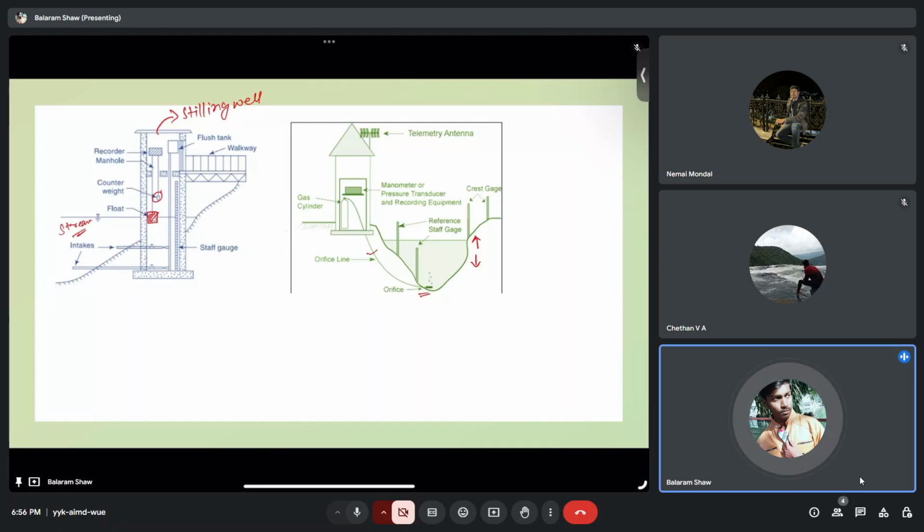And from that rating curve that I just mentioned, which is a very simple thing but very important, and gives a significant amount of information, we get the discharge, that is, how much stream flow is happening in the river or streams. The rating curve for a specific stream location is developed by stream flow measurements at many different stream gauges.